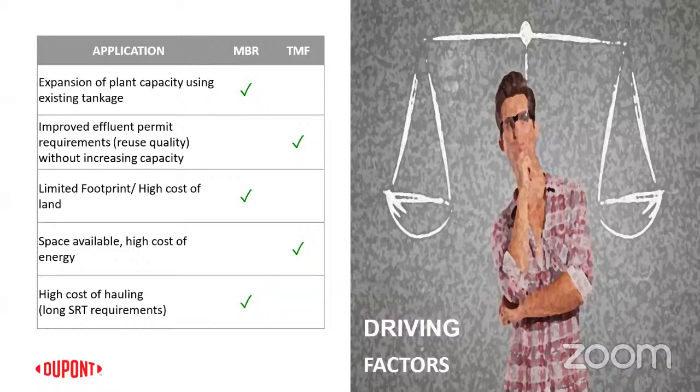Generally, MBR works in the range of MLSS from 5 to 15 grams per liter. And the SRT, again depending on the wastewater, can be from 5 to 40 days. The sludge production is only like 0.1 to 0.7 kg SS per kg BOD removed. So that's the level that it is. The operating flux, like I said, the throughput per unit area of the membrane, is around 15 to 45 units. And the pressure it works at is around 60 kilopascals, so 0.65 bar. Sorry, 6.5 bar. That's the maximum it would need.